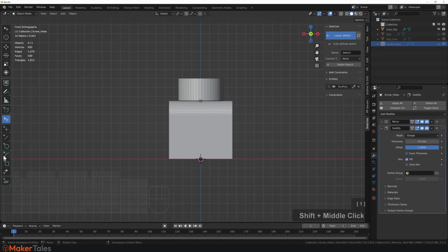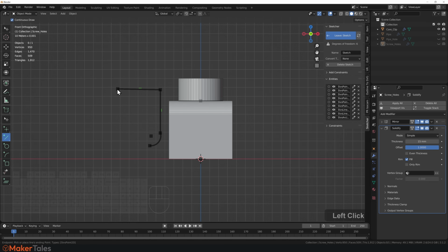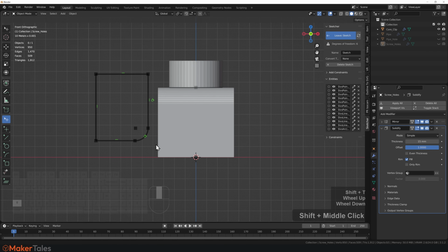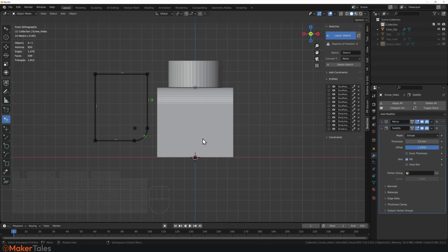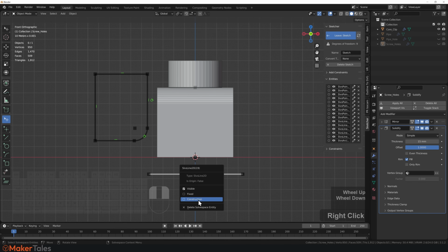And now that we've done that, what exactly are we trying to do? Well, we have an arc for sure that's going to be like this. We have a line that's going upwards, and then we need to create a cutting object that's going to cut the profile like so. Now, these two here, they're going to be tangent to one another, but we don't know if this one's tangent at all, so let's not bother with that. Now, we don't have any references, unfortunately, that we can be using here, so we're going to have to create ourselves a reference line. So let's create ourselves a reference line right there. Turn this into a construction line.